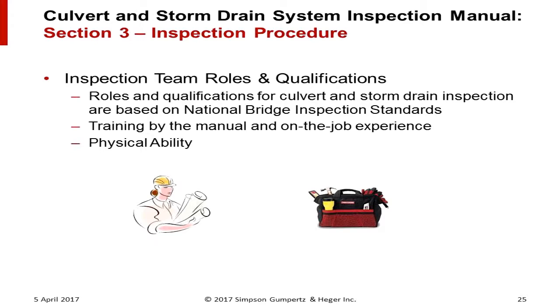The inspection team roles and qualifications now look similar to bridge inspection. Training is recommended in terms of understanding what's in the manual and the rating system, so there should be some in-house training. There's also an advisory on the physical ability required to perform culvert inspections. They're a little more strenuous than bridge inspections.